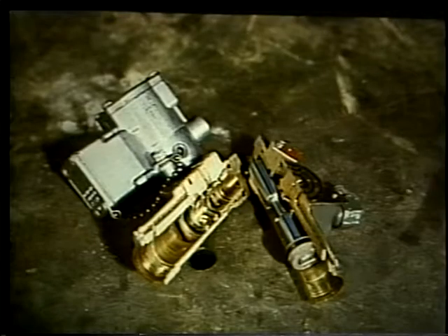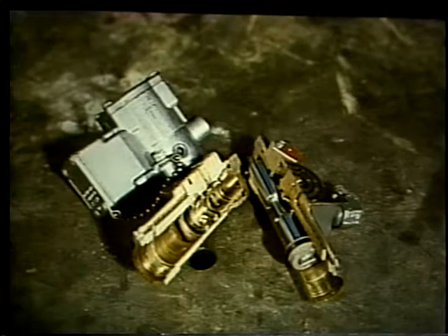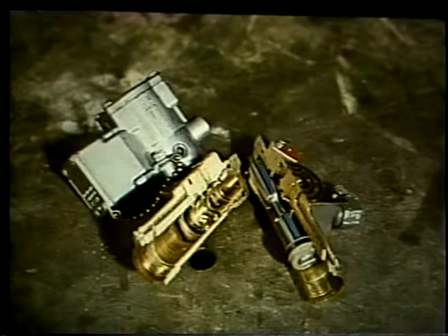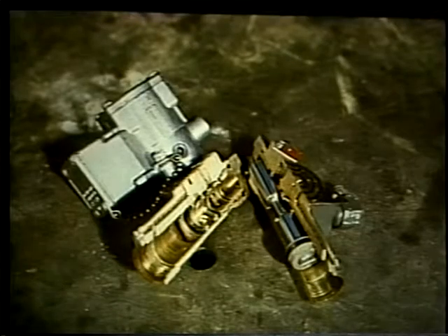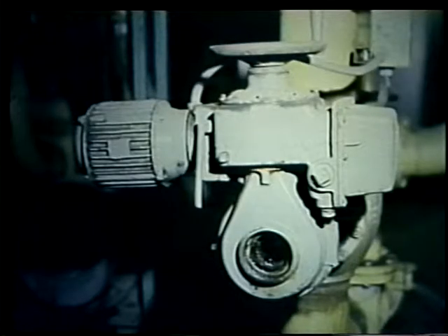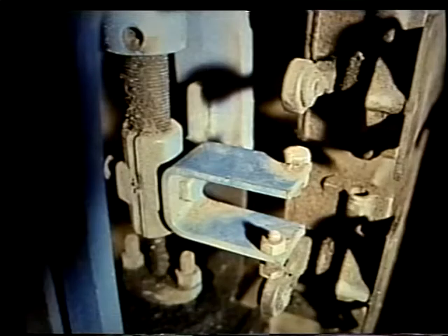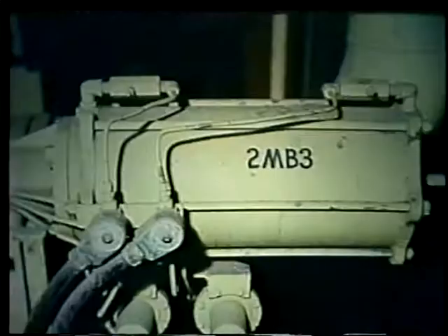Electric solenoids are usually used for remote operation on short stroke applications, usually a quarter of a turn or less. Electric motors are connected to the valve stem. They're usually run at low speed, but are high powered. When the motor is energized, the stem starts to rotate. A limit switch stops the motor when the valve is fully open or closed.